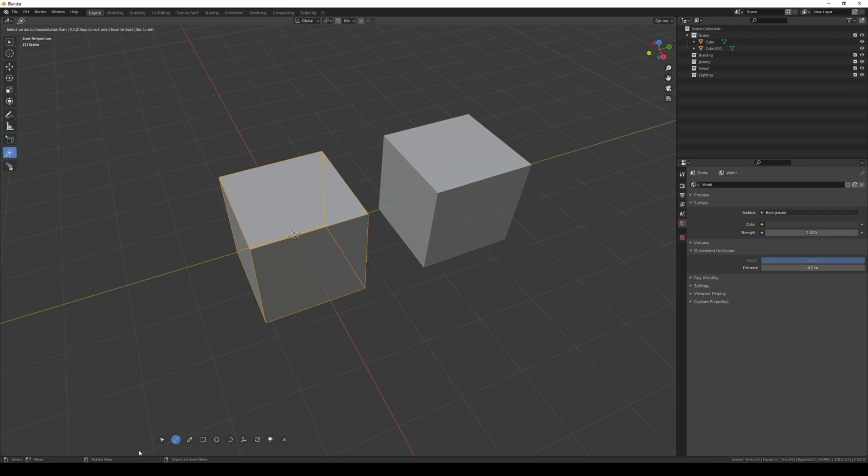Looking along the toolbar, we have a selection mode, which we'll talk about in a minute, the measure guide tool, line drawing, rectangle, circle and arc tools. We've got our move tool, and now we've got these two extra, rotate and face extrude, which we'll go through in just a moment. We also have another exit button, which allows you to exit Construction Lines. And you'll notice under each one in brackets, you also have the hotkey.